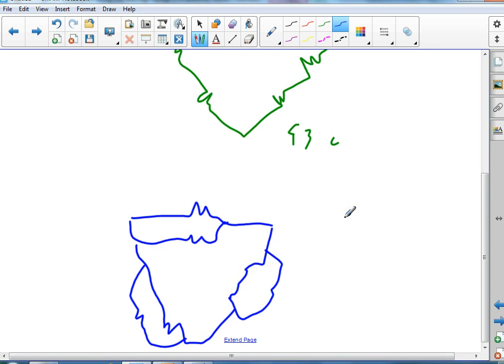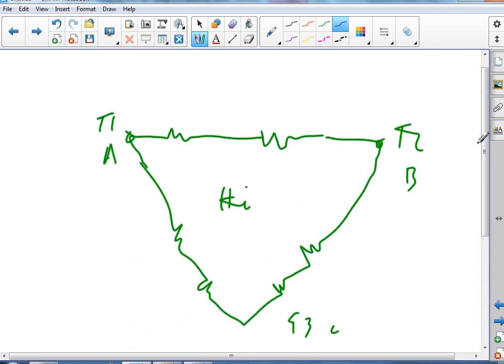If I took my delta and I had 480 across those two windings, I'd have 240 across each winding, right? But we just showed that we only had 120 across our windings when we were Y connected, right? So delta connected, I have more voltage across each of the windings. That may or may not be good.